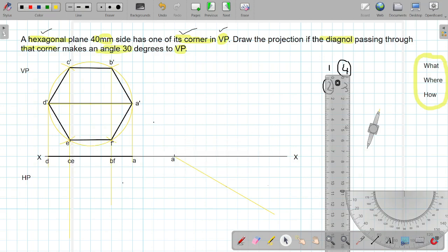So once we got this reference point, what we will do is, we will take the measurement of this point from point A to point D. So measuring the distance from point A to point D. Now we'll keep the compass at point A here and we'll make an arc on this particular line. So wherever this arc is made, this point will be named as D.